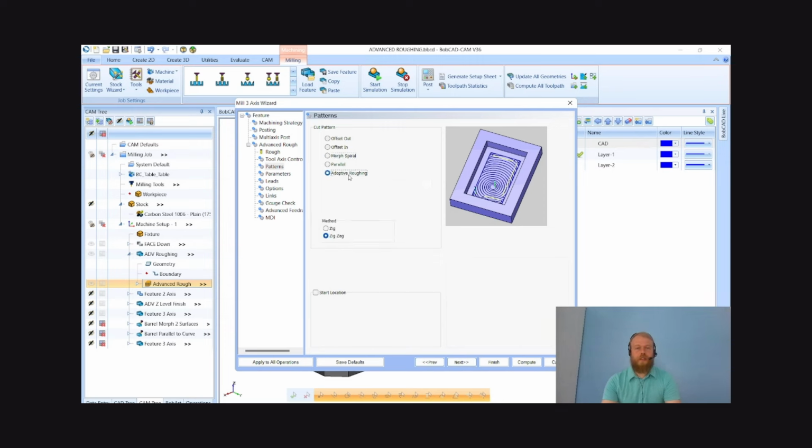And then adaptive roughing, again, constant tool engagement, another high-speed machining operation, where normally with these two operations, the methodology is the tool will come down at usually the total depth when you're getting into softer material, going down to the full depth and just hogging out material as best as possible there, best optimized cycle times, things like that, and keeping constant tool engagement.